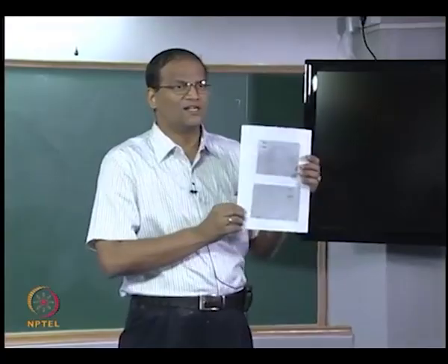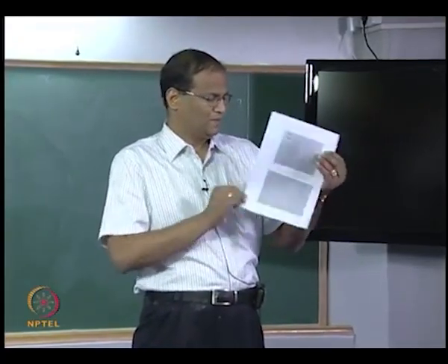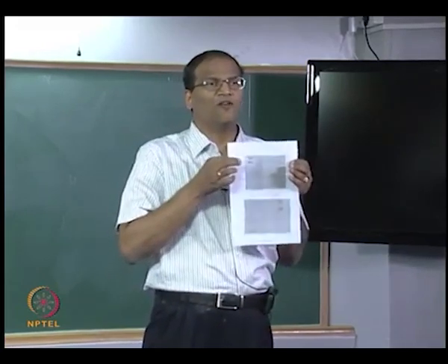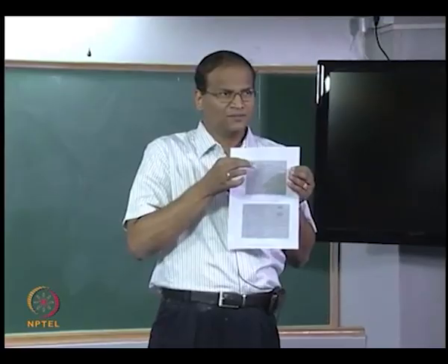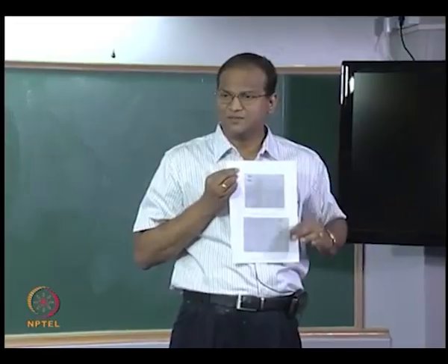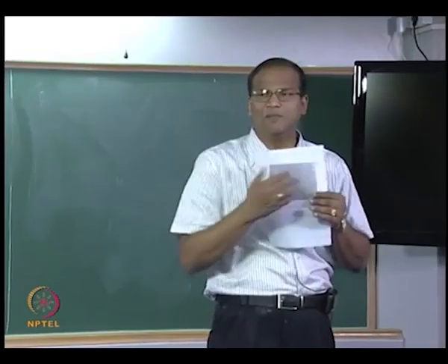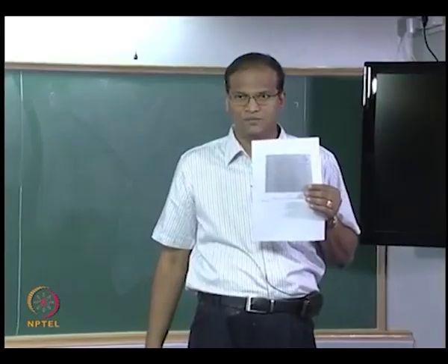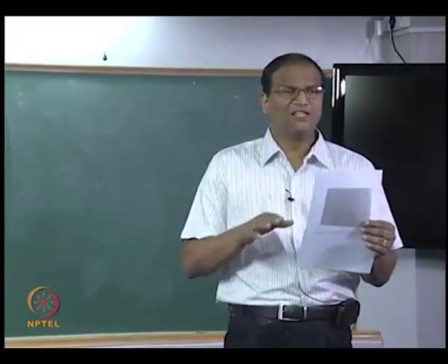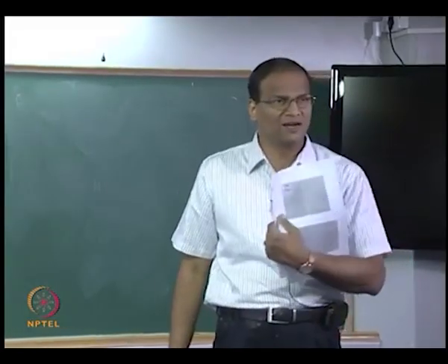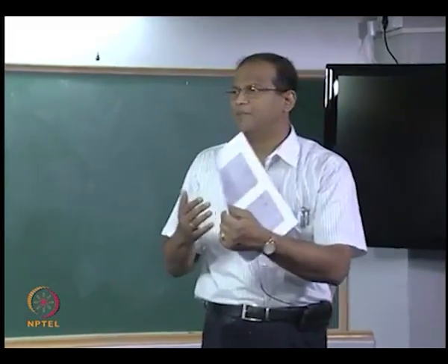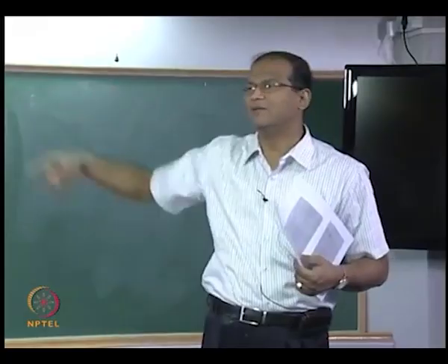Okay. So please look at these charts. One view factor is between 2 parallel rectangles, and the second one is between 2 parallel discs, and on the back side we will have perpendicular rectangles. These are some 3 simple configurations, you can do other configurations also, but with this simple configuration if you have a perpendicular rectangle and parallel rectangle, then you can solve a furnace problem, right. If it is a cuboid or something, all are either parallel or perpendicular, then other view factors you have to get by algebra.